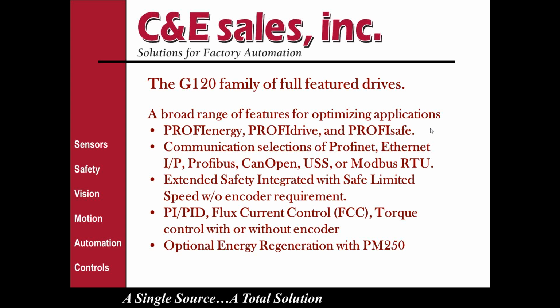This has a big advantage on widely distributed applications, where we can run the safety stops into the controller, communicate that over either Profibus or Profinet to the drives, and still have a high degree of safety at the drive end. This allows you to eliminate, in many cases, the use of contactors before or after the drive, which can greatly reduce both panel size and the cost of the projects.